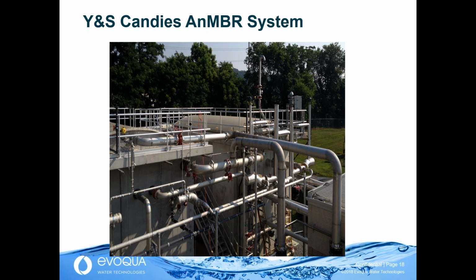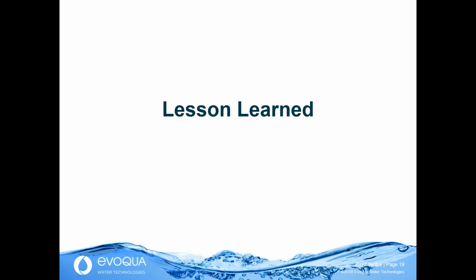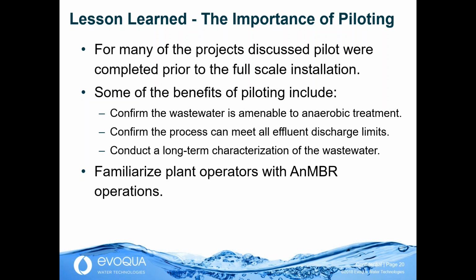The organic removal increased from previously getting about 60% COD and BOD removal to now getting 97% COD removal. So they have no worries about not meeting their discharge limits like they did before. And since the clarifier is not being used anymore, they don't have any concerns with odors.